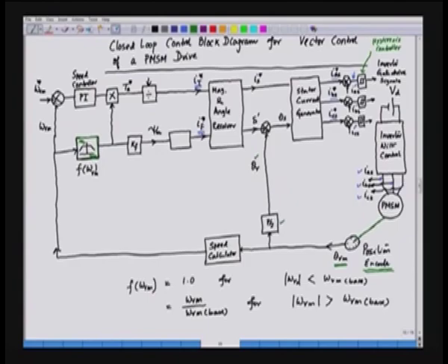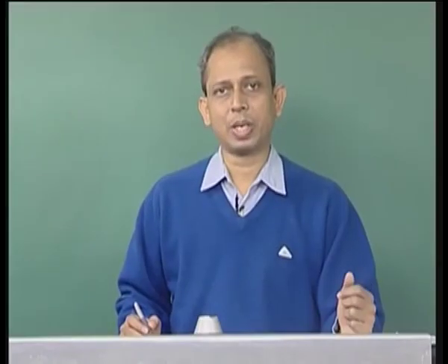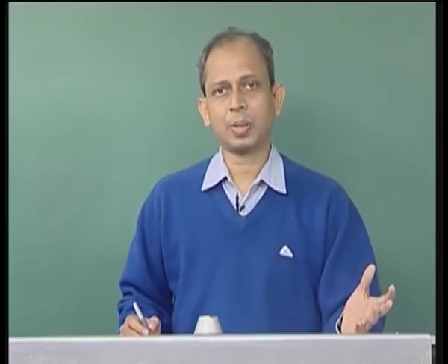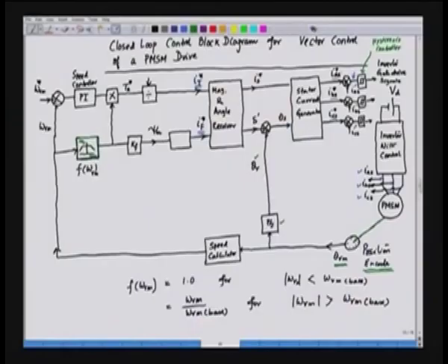In the model, we have the electrical rotor angle theta r, and theta r is used for transformation into IAS, IBS and ICS. Hence, for transforming this into 3-phase current, we need the electrical angle theta r, and this is added with delta prime to give us theta s for the reference current generation.